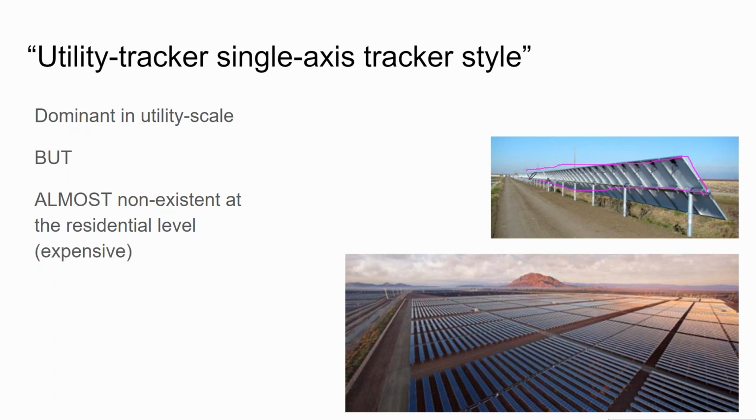And so single axis tracking is like, okay, well, we're only doing one row of modules, so we don't need very deep foundations. We're making better use of our module frame. And so the added cost is, whether you're going 2 modules deep and having a second row of piles, or 1 module deep and having 1 row of pile, you're paying for those piles either way.